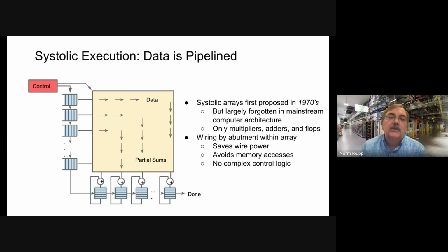And what's not shown in this figure is that at each intersection, there's a data value that gets multiplied with the data that's coming from the left and added in the flow that's going down to the bottom of the array. And for our first TPU, we also added a recirculating accumulator at the bottom, so we could accumulate more than 256 sums.